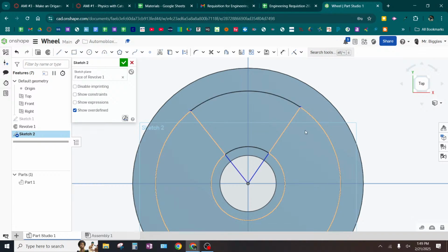Now, you said 6. How many degrees are in a circle? 360. So how many would be 1/6 of that? So each gap has to basically be allocated 60 degrees. Does that make sense? And that's not just the gap, because if every single gap or hole was 60 degrees, I'd have 360 degrees of holes, which is also known as deleting everything. But a spoke plus the hole combined would be 60 degrees. So I'm basically going to be drawing 60 degrees worth of space.